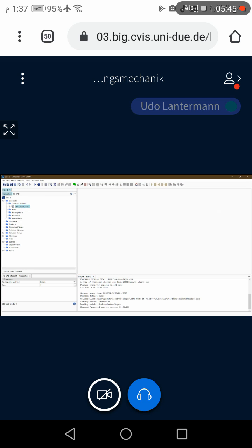So you have to click with the right mouse button on this 3D-CAD models, the one which is highlighted in blue now. Okay? And then there will be an option New. So choose this New and this 3D-CAD model 1 will be created.